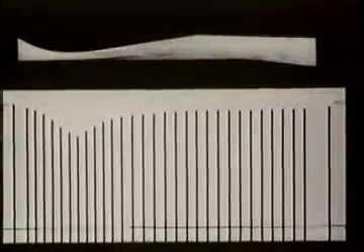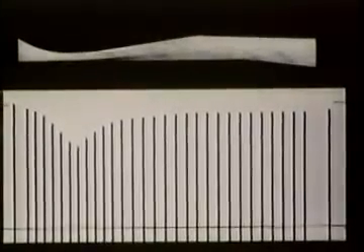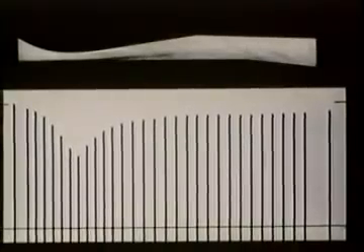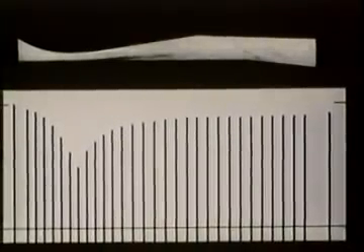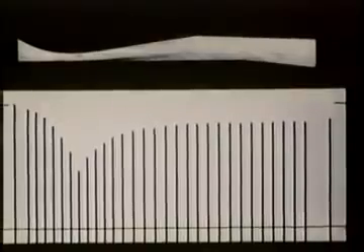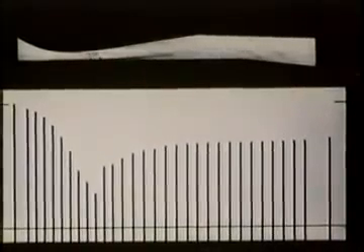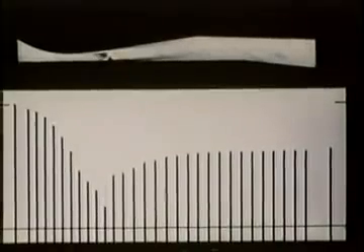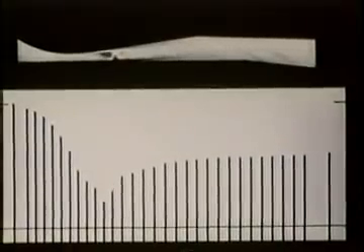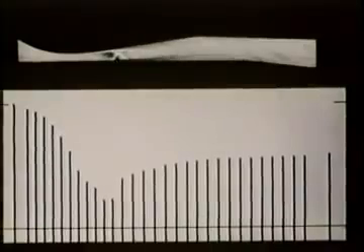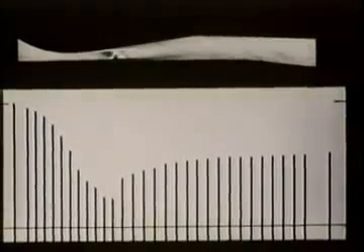The difference between this symmetrical flow and this unsymmetrical one is that now the velocity is sonic at the throat. This transition to sonic flow at the throat with all of its consequences is called choking.